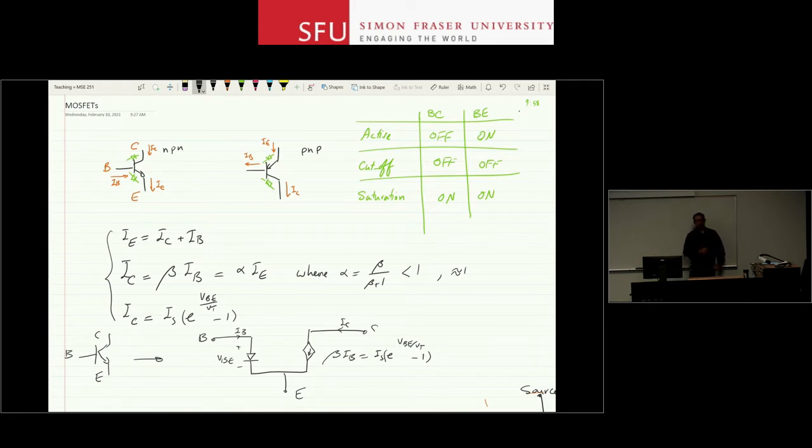So in practice, a lot of you guys will later on go and design circuits on boards. And then you may not design an IC. And therefore, you need to know about BJTs most likely better than the MOSFETs. But MOSFETs, on the other hand, are used more and more in a lot of new applications, like in power electronics. There are certain advantages to using MOSFETs, power MOSFETs instead of power BJTs. And we have to learn about them as well, even though we may not design an integrated circuit.